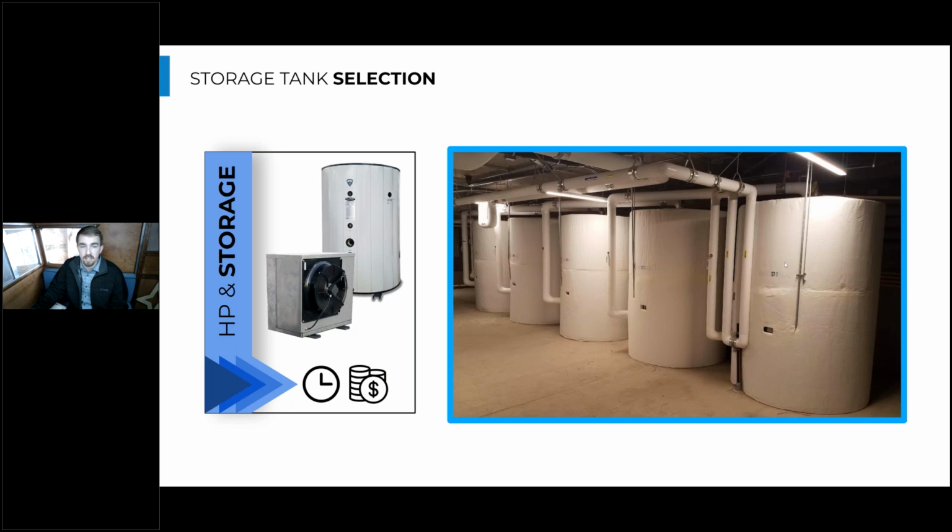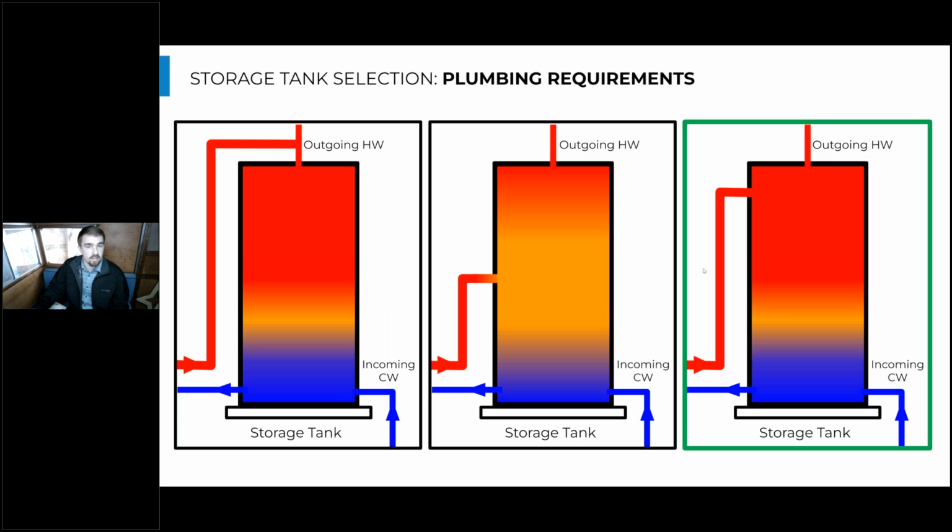Like if everyone was to get in the shower at the same time in the morning, the storage would supply most of the hot water while the heat pump trickle charges the storage throughout the day. And these are probably the top 3 ways, or the 3 most common ways I've seen storage piped up in the field.